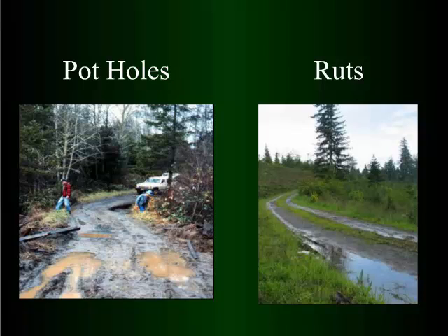This example of ruts, you can see water gets caught and just keeps on coming down the road. It's starting to cut a little bit here. It's ponded up here. Whenever you have standing water, your subgrade gets saturated, and it's pretty easy to get subgrade deflection. This is surface deflection, basically with the ruts. But that can compound, and that deflection can go down deep, and you can end up ruining a road by deflecting the subgrade. In this case, it looks like it was a gravel road at one time, and they're in danger of losing their investment in that rock.